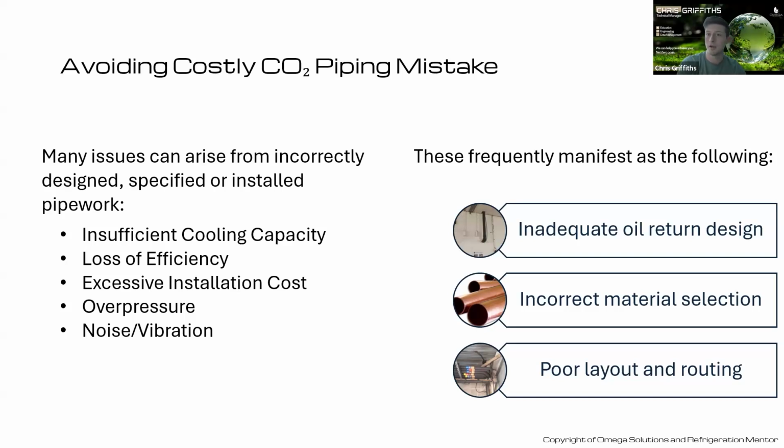And then if we undersize our pipework, or if we have too many short radius bends, we can get noise and vibration occurring from pipework, particularly on liquid lines. If a liquid line is sized too small and our velocity is too high, when any valve decides to shut fully, all that energy has to find somewhere to go. It's not just going to stop moving without dispersing that energy. That will go into the walls of the pipe and into the valve body. It will potentially corrode the inside walls of the pipe. It will damage that valve over time, and it's unwanted. It will be costly to replace.